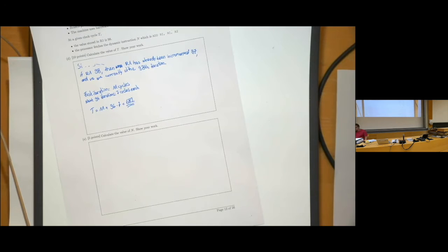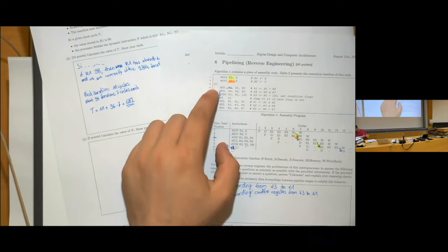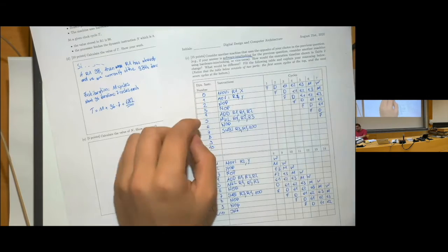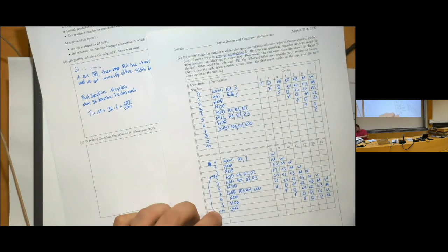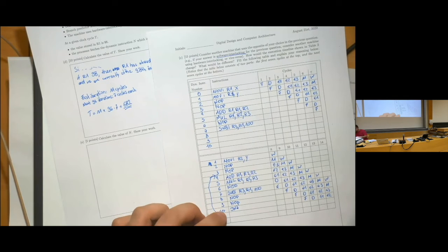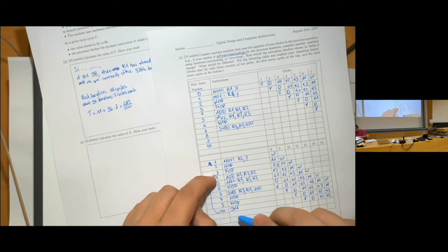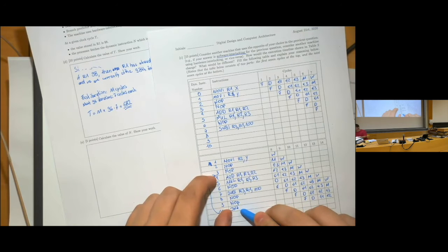Yeah, it's a great question. So I'll repeat it for the recording quickly. The question was if you have this jump here, this solution assumes that there's no delay, or well, stall wouldn't be accurate, but no delay between here and starting the addition instruction here, even though we need some time to probably even realize that this is a branch.